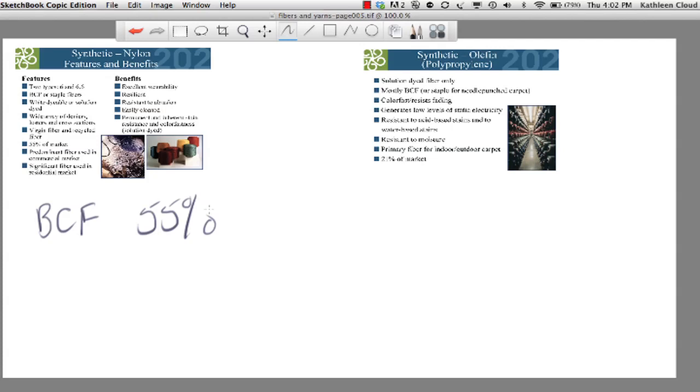There are two types of nylon used in the carpet industry. Type 6, it's up here on the top, and 6.6. They each have unique physical and use properties. Nylon comes in a wide array of deniers, lusters, and cross sections that provide different performance attributes and is offered as white dyeable. Think about the coloration possibilities here. And solution dyed.